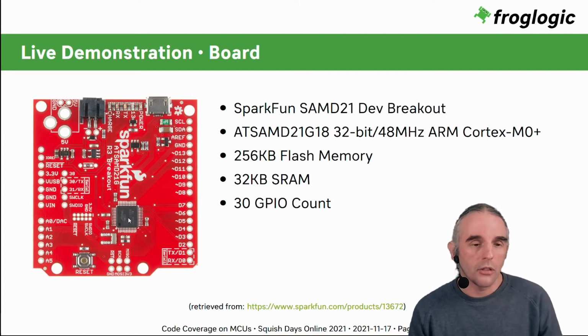As you can see on this board, there is no memory, there is no flash, there are practically no additional hardware here. This thing here is the microcontroller, this is just a button, and these things here are just some voltage level converters. There are not even additional electronic parts like crystal oscillators, because everything is put inside of this chip.